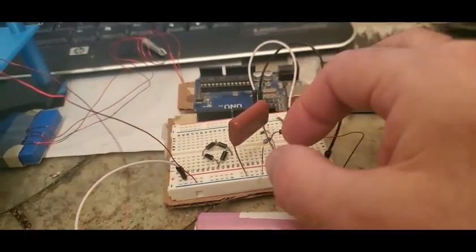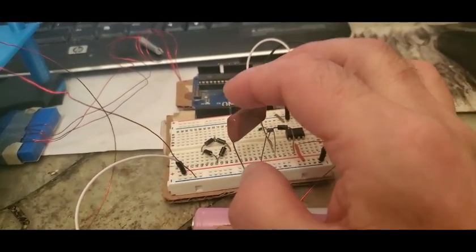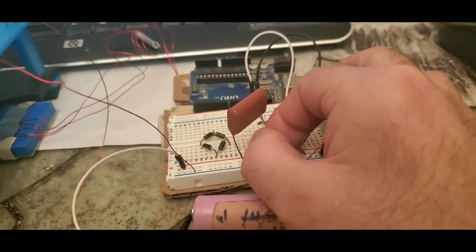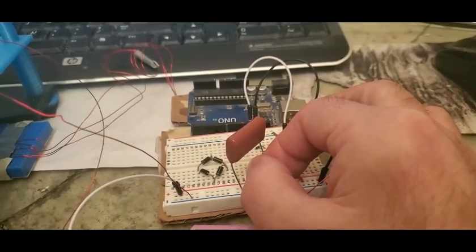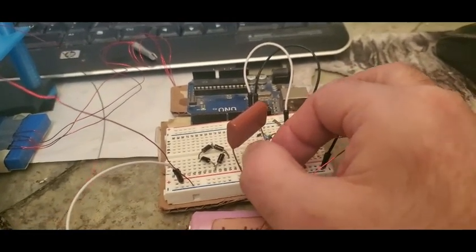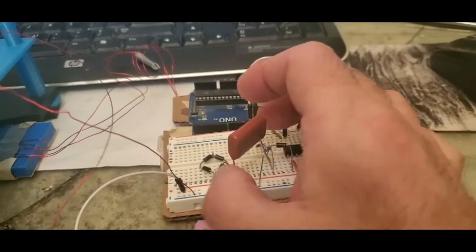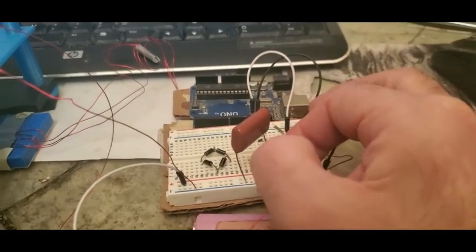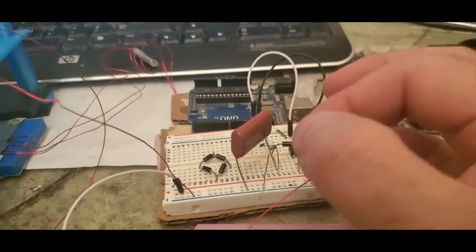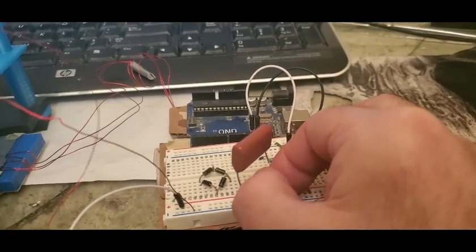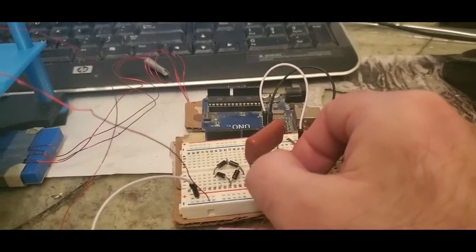Now, you can look at it without a resistor across the cap, or we can put a resistor across the cap. And what I've done is I've looked at different resistances, and I'll try and touch on that very briefly. And in fact, one of the things that'll be fun is we can just put a dead short across here. And we'll see what happens with the motor then. And we'll talk real briefly about why that is. So I don't know what this is. Let's put in a 1K ohm, and then we'll look at the spike, and we'll see what we get.